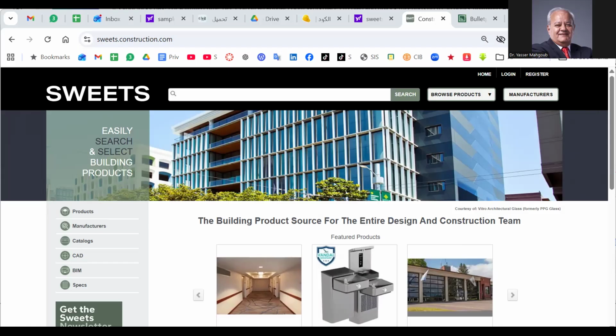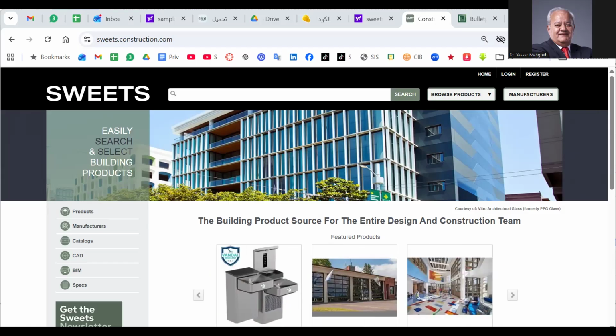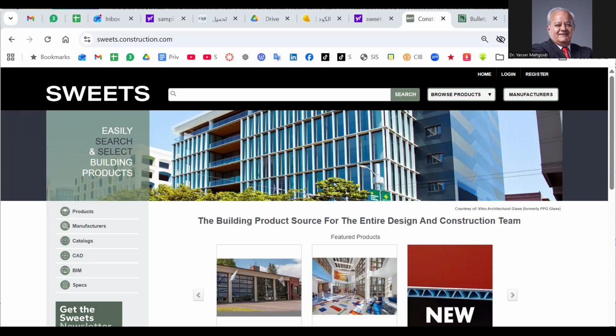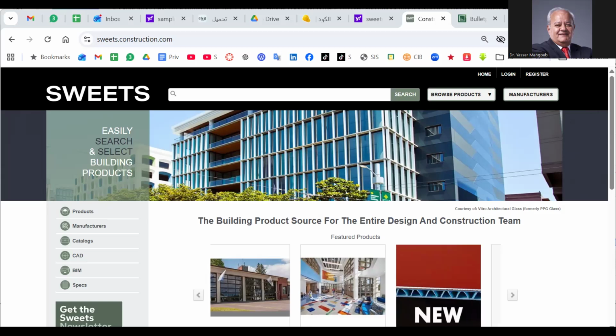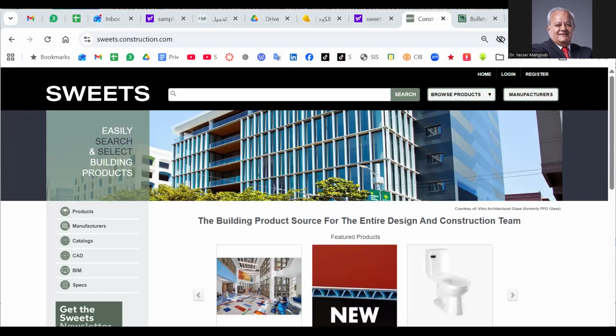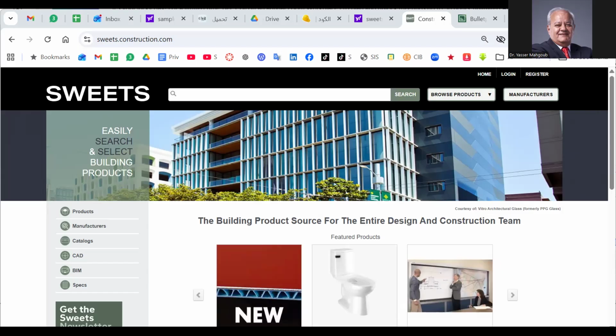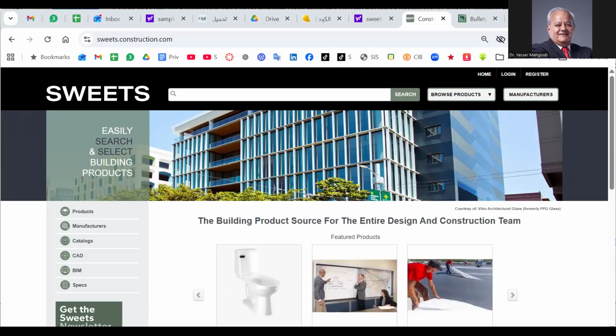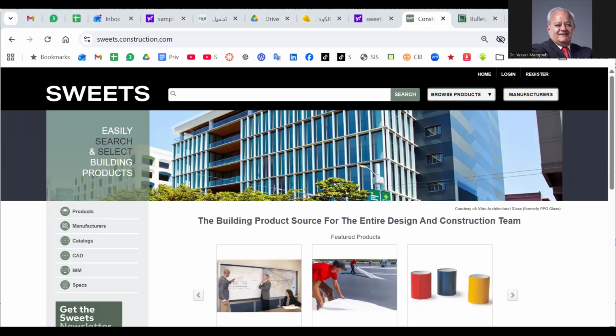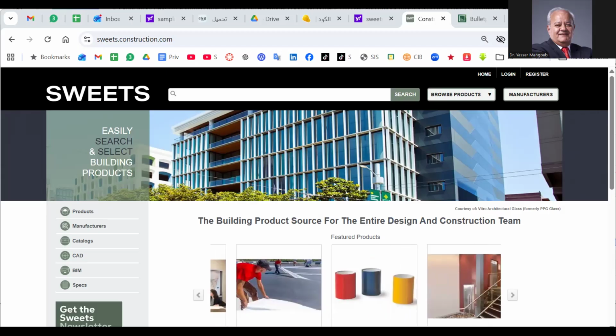Toilets details, and you have to draw all the tiles exactly as you want them in plan and elevation, section, details, dimensions. No horizontal dimensions in sections and elevations. Horizontal dimensions are only in plans. Only vertical dimensions.